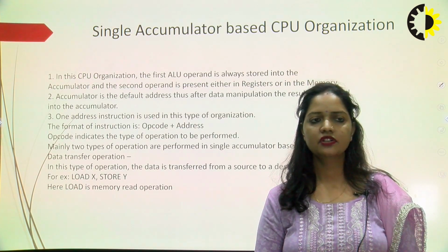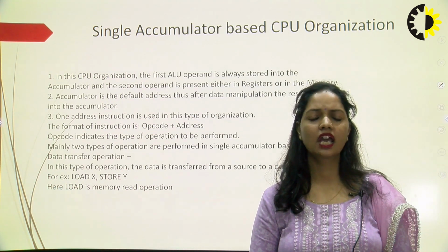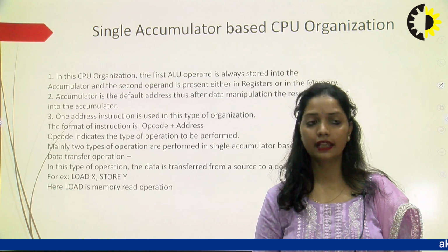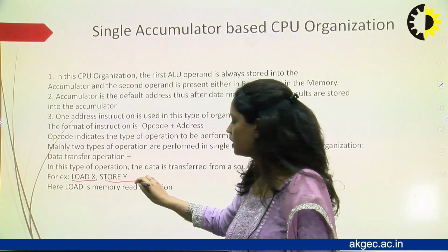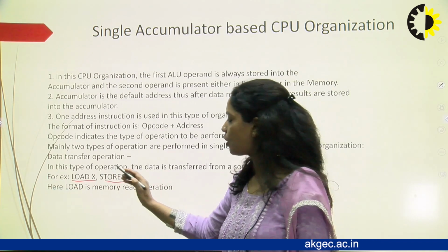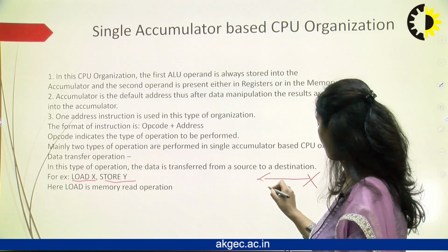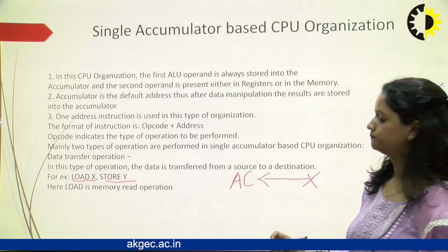A one address instruction is the example of this organization scheme, and we have certain instructions like load X and store Y. Loading means that we can copy the content of operand X into the accumulator AC.